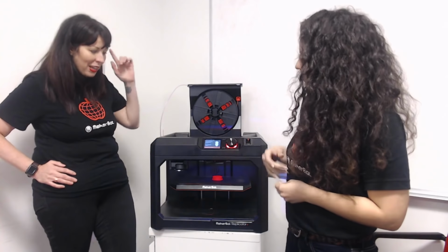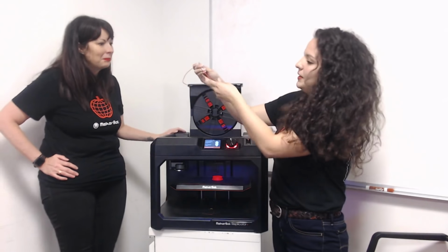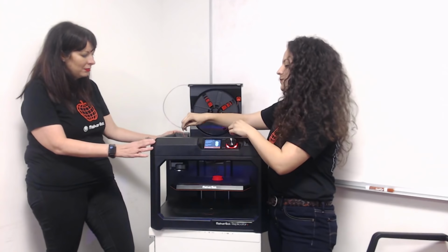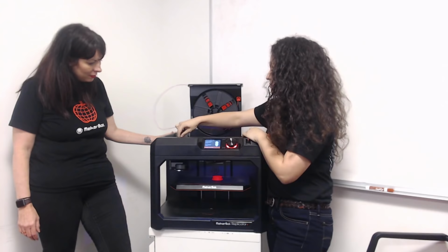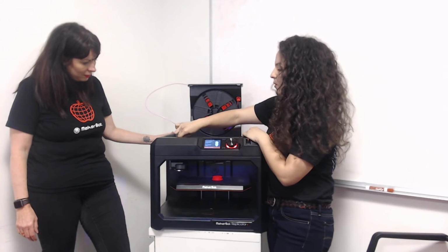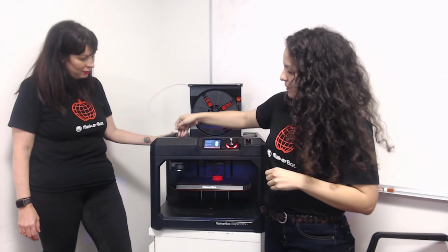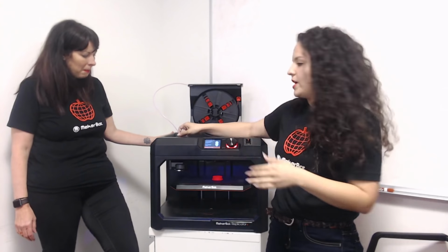Awesome. So that sound means our filament is ready to go? Exactly. Now I'm going to take the filament here, and I'm actually touching the physical filament. I'm going to feed the filament through the extruder. We already have one on here. I'm just going to feed it through until I feel the extruder actually pulling the filament in. And I like to keep my hand on the filament to make sure it's getting pulled in all the way.